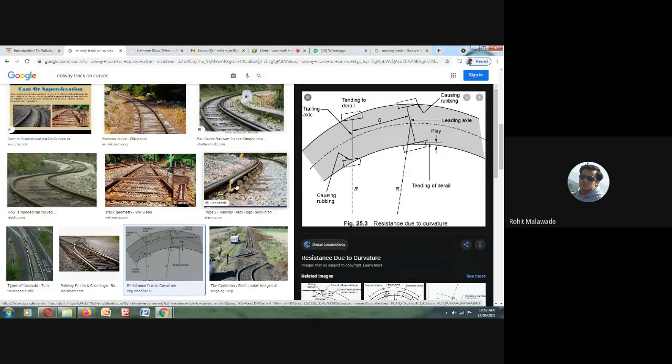It is going to create some undulations and some depression on the rails. As a result, it is going to create a non-uniform and unsmooth ride. If the ballast or subgrade is not filled properly, such kinds of stresses are going to develop.